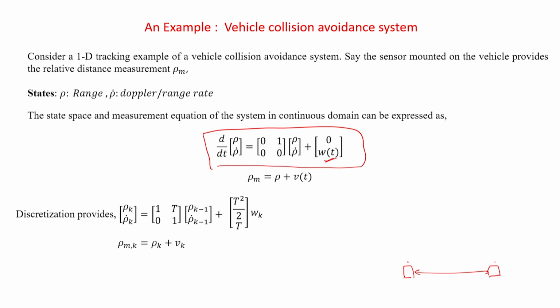Okay. And the sensor, whether radar, camera, lidar, whatever you have installed here, gives only the relative range measurement by some means. Camera won't give it, but it is possible if there is LiDAR and such things. I won't use the position, because if you want to use position, you need a coordinate system and you need to know the position of your ego vehicle with respect to it. So, the best thing to do is use the relative distance or range. It is contaminated with white Gaussian noise.